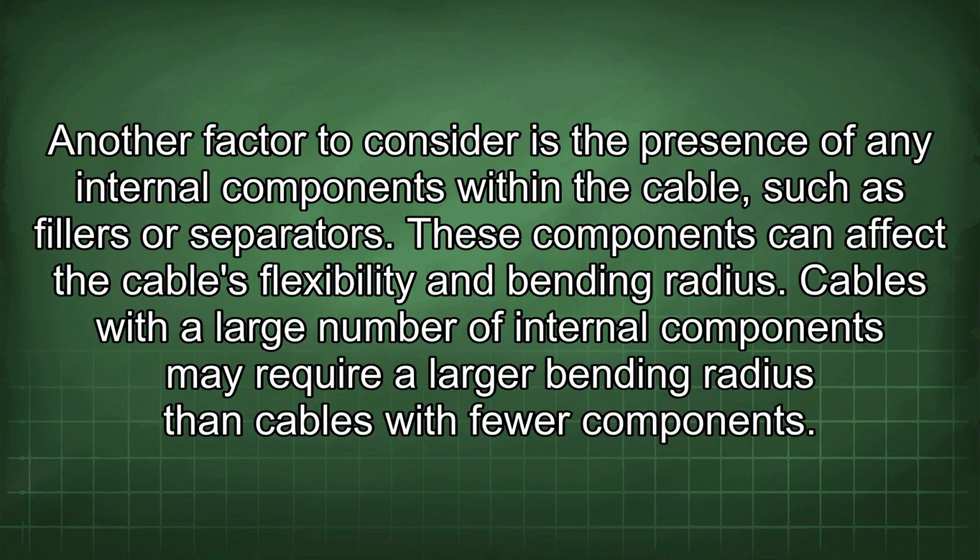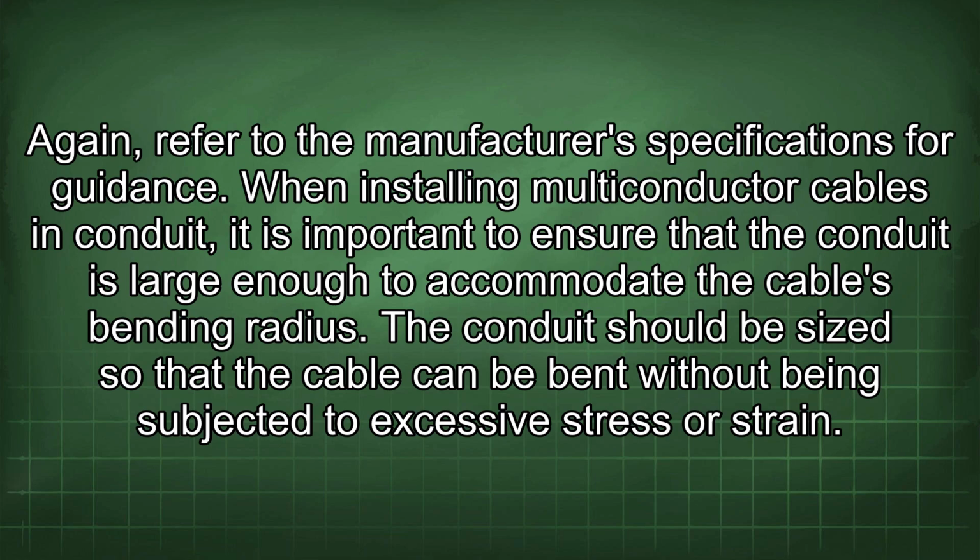Another factor to consider is the presence of any internal components within the cable, such as fillers or separators. These components can affect the cable's flexibility and bending radius. Cables with a large number of internal components may require a larger bending radius than cables with fewer components. Again, refer to the manufacturer's specifications for guidance.